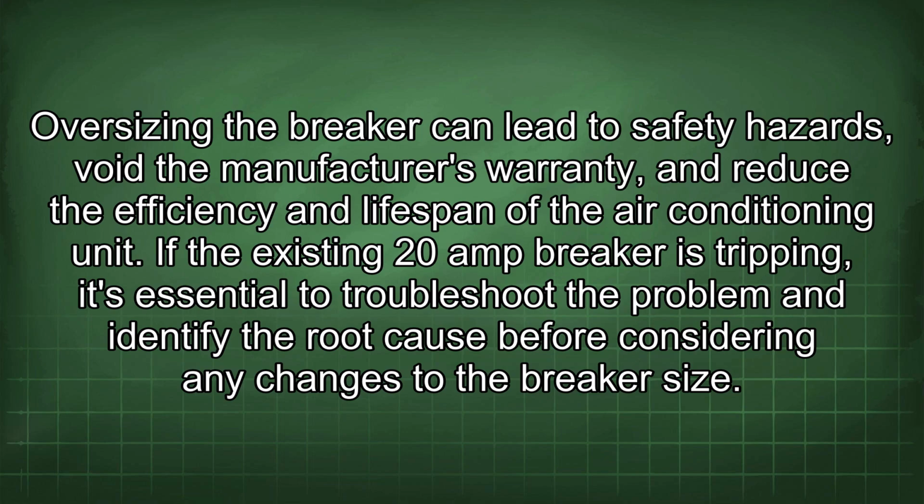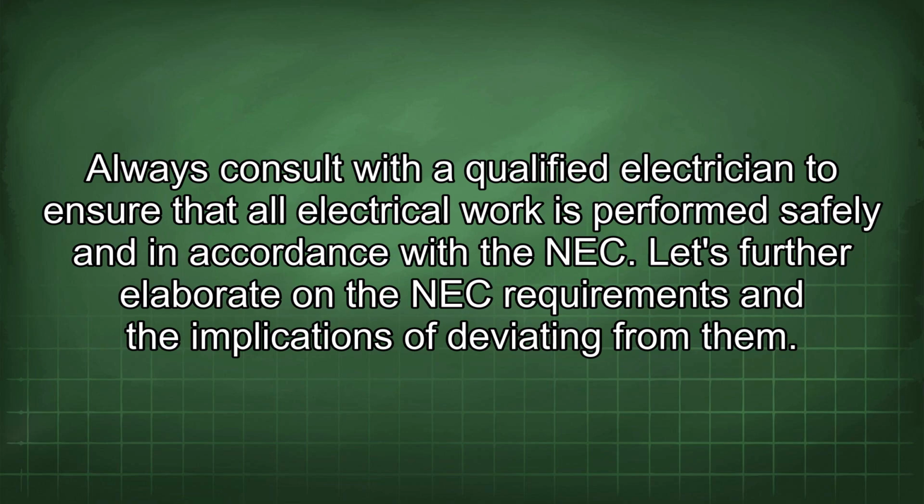If the existing 20 amp breaker is tripping, it's essential to troubleshoot the problem and identify the root cause before considering any changes to the breaker size. Always consult with a qualified electrician to ensure that all electrical work is performed safely and in accordance with the NEC. Let's further elaborate on the NEC requirements and the implications of deviating from them.